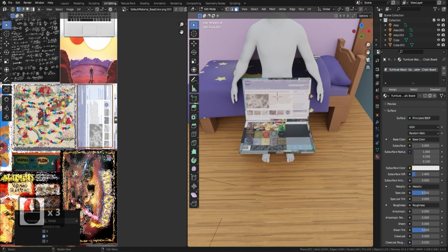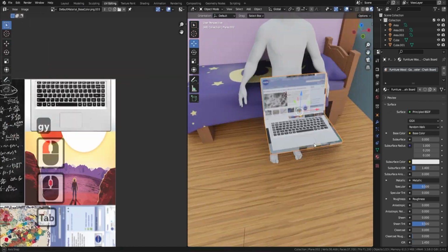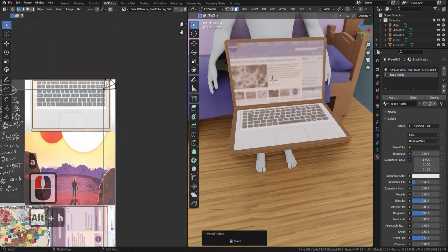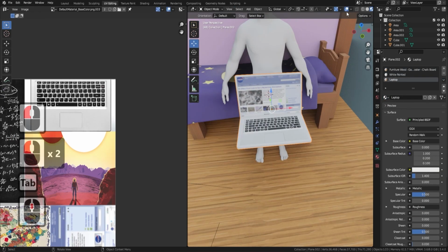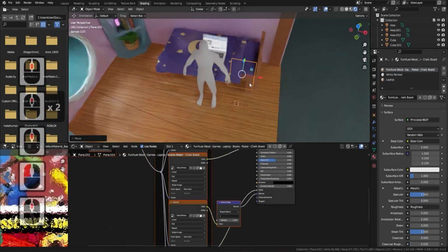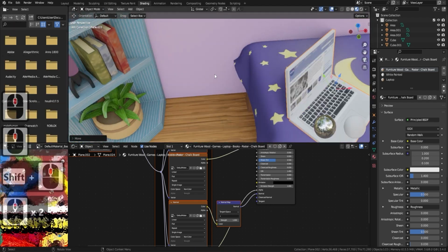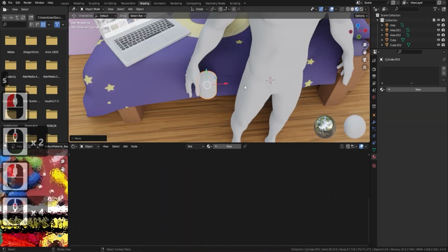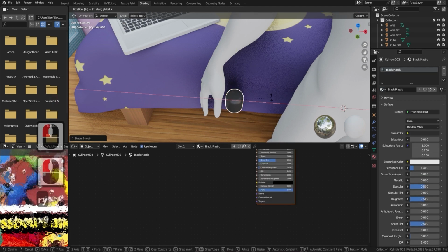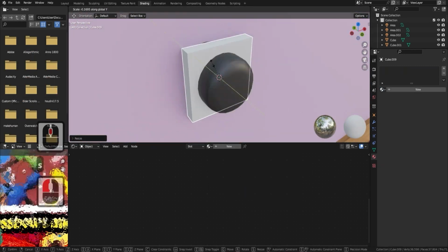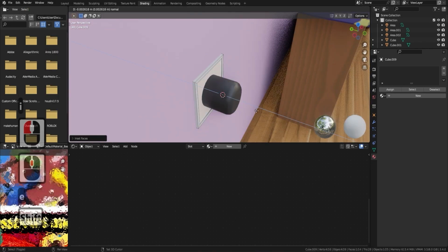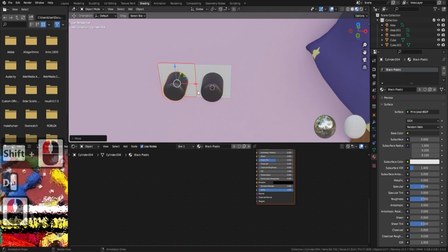Again, with the texture here, all I did is take a screenshot of something like the NASA website and plonk that into my texture map. The only thing that's important, as I said earlier, with the texture maps is to make sure that you are creating things like roughness, metallic, normal maps, and any emission that you might have. That's the main thing that you need to get right.